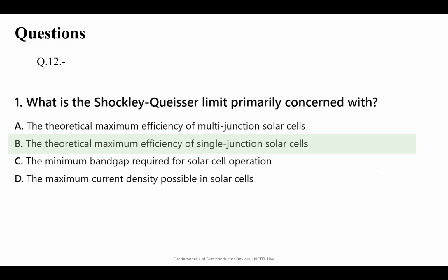That is correct. According to the Shockley-Queisser limit, if you make the perfect silicon solar cell, still your efficiency cannot be more than 33%, primarily because your silicon band gap is 1.1 eV and your solar spectrum peak is around 2 eV. So all that extra energy is getting lost, and mainly because of that your efficiency is reducing.